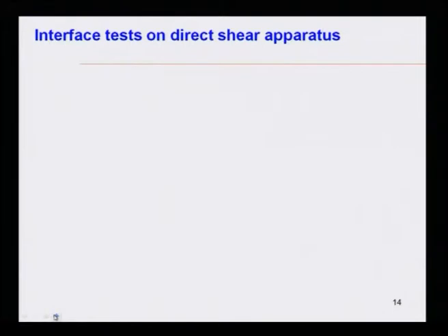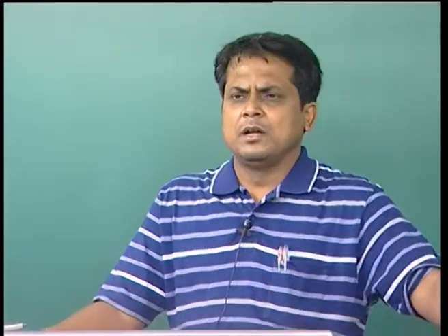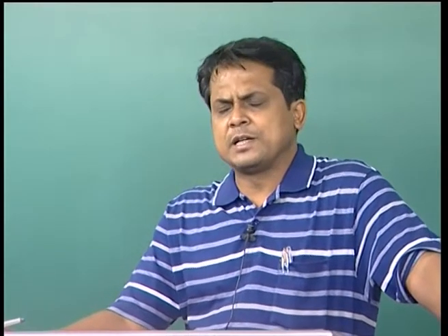Now, this is one way of direct shear test, by which you can find the shear strength parameters C and phi. Direct shear test is more applicable for drained tests, where development of pore water pressure may not occur. At that condition, drained test, u is equal to 0. We have discussed for sand. For sand, C is equal to 0 as it is a cohesionless soil. So, phi is equal to phi prime.